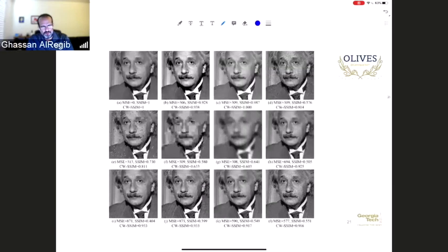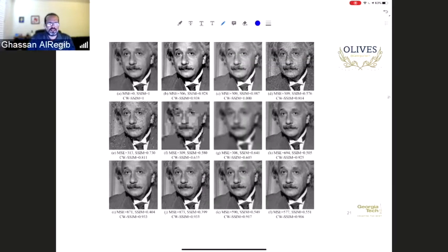So here is a diagram from the original SSIM paper. For each one of these images, it shows three measures: the mean square error, the SSIM, which we'll study later on, and the complex wavelet SSIM, which is really an extension to SSIM. What we need to worry about at this moment is only the first number, the MSE. If you look at the first image, this is the original image, so the MSE is 0. And then all the next images have some degradation in some way.